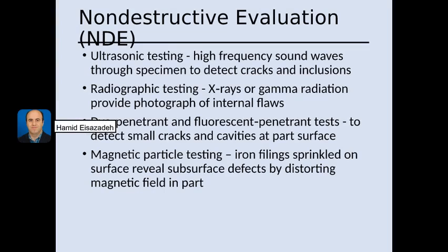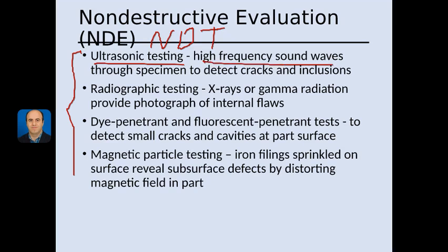Here we have non-destructive evaluation methods, NDE, sometimes we call it NDT, non-destructive testing. And we have 4 methods. Each method should be explained in one session, but we don't have that much time, and it is not the scope of this course to go through this process in great detail. Here we have ultrasonic testing, where we use high frequency sound waves to detect cracks and inclusions inside the part.